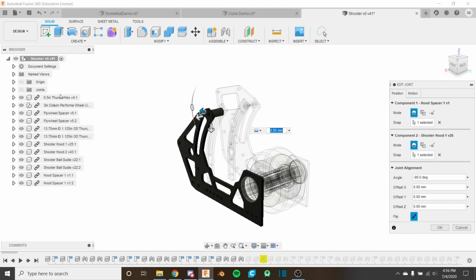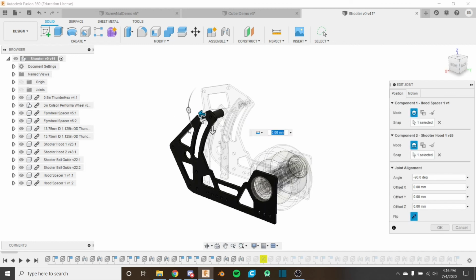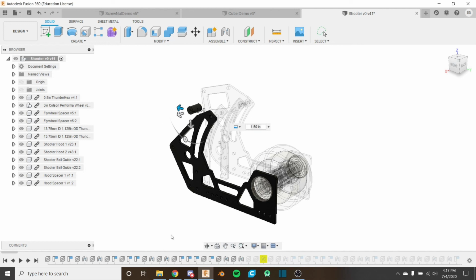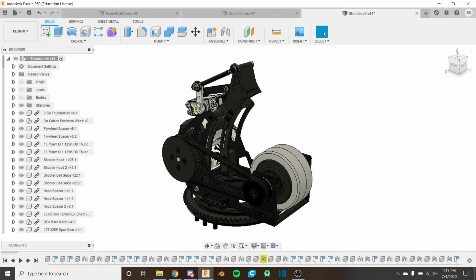It's how much was in at that time, and I could edit it here and it would change everything downstream. So if I made it rotated, or I moved it over or something, it would change everything else after that, and it would update. So it's really important to make sure everything's built properly so you can go back and edit stuff that you did before, and Fusion 360 will recalculate it properly in the way that you're expecting it to.